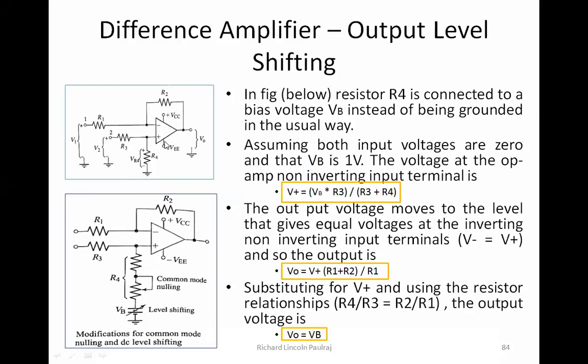And these terminals do have their associated resistors, which are R1, R3, and R4, okay, towards the input side. And if we are talking about the gain, then it's wholly determined by R1 and R2, right? So we saw a small mechanism where we can match the resistor ratios, R4 by R3 is equal to R2 by R1. So these resistor ratios we were maintaining.